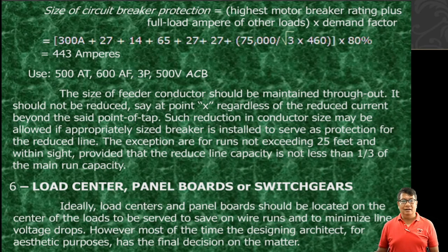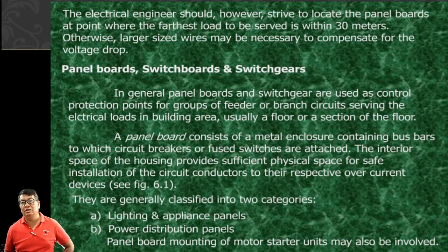So basically, we should have to locate our load center. Yan nga po ay tinatawag natin na load center kasi kung saan natin makikita yung pinakamalaki yung load, then try to determine saan po yung sentro ng load natin, doon sana ilagay natin yung mga load centers natin. Okay, so the electrical engineer should, however, strive to locate the panel boards at point where the farthest load to be served is within 30 meters. Okay, so dapat yung farthest load natin is within 30 meters. Otherwise, more than 30 meters, baka more than 3 or 5% na yung drop natin.